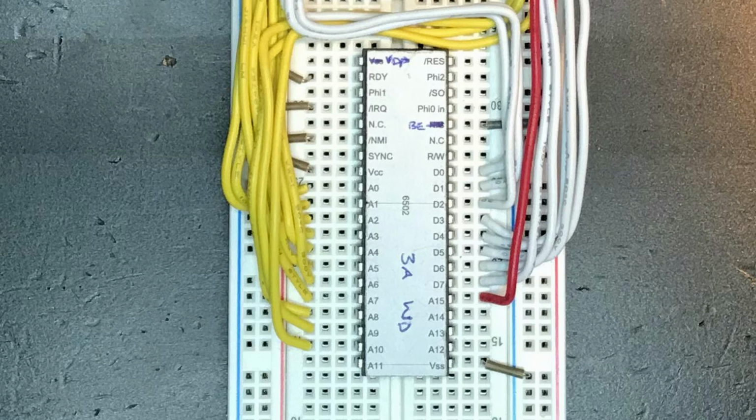So on the 6502, first we're going to connect up power, that's 5 volts input on pin 8 where it says VCC, and then ground on pin 21 where it says VSS. Pin 1 is the vector pull on the newer 6502. It's an output that we're not really interested in, so we'll just leave it. Pin 2 is the ready pin, and we need that one high, so we connect that to the 5 volt rail.